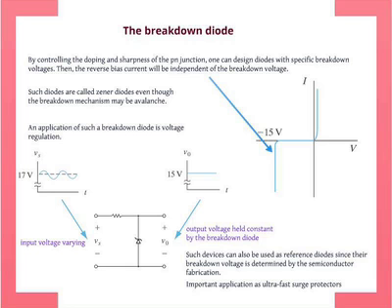If you recall, in your AC to DC converter, it is never flat. In fact, we will look at rectifiers later on, so we will revisit that. But you'll always have some ripple going on top of it, and this just has to do with the capacitive response of your circuit, the LCR response, if you go through it carefully. In any case, what you get is some sort of voltage here, which has a DC bias value, and then you have some ripple which runs on it.